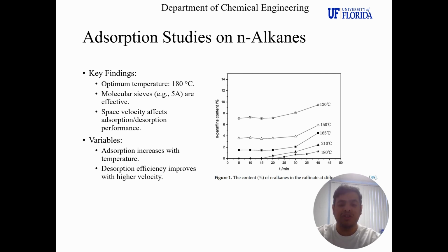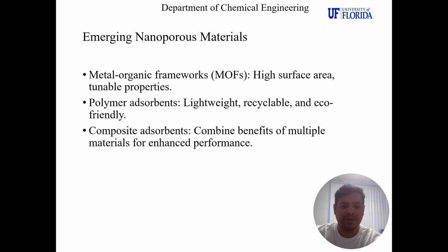Optimal adsorption was observed at 180 degrees Celsius with 5A sieves. Space velocity studies showed higher desorption rates at increased flow rates. Graphs illustrate the relationship between temperature, flow rate, and adsorption efficiency, emphasizing the need for precise control of experimental parameters.